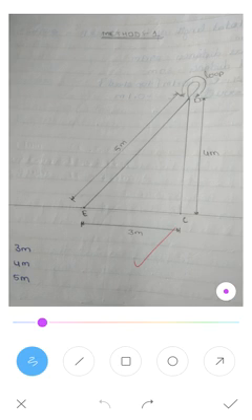To erect the perpendicular at point C on the chain line, establish a point at a distance of 3 meters from C. Put the zero end of the tape at C, and at a distance of 4 meters you have to take it in this direction. So you have to make an arc.